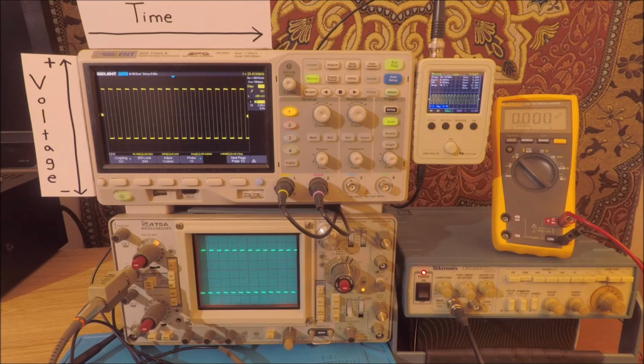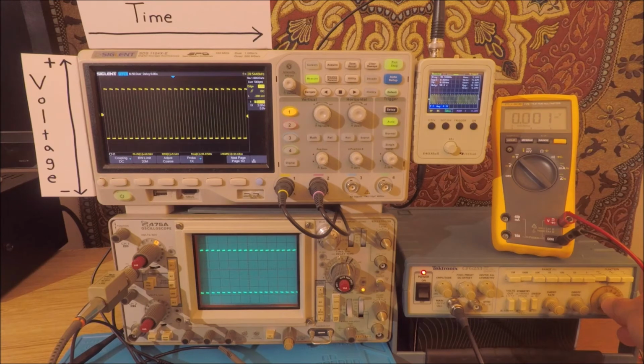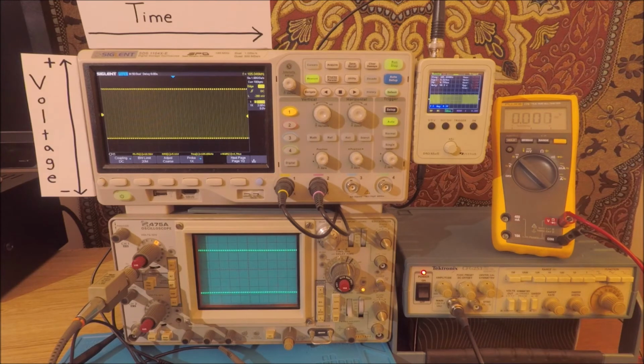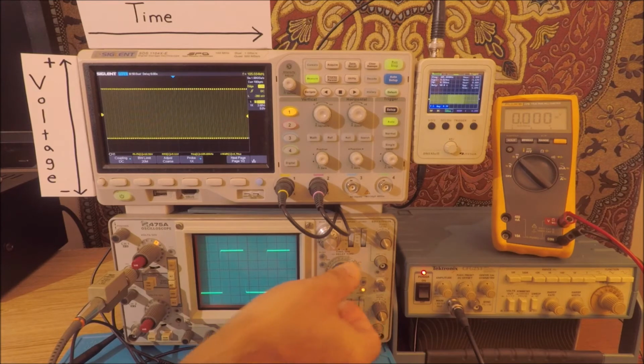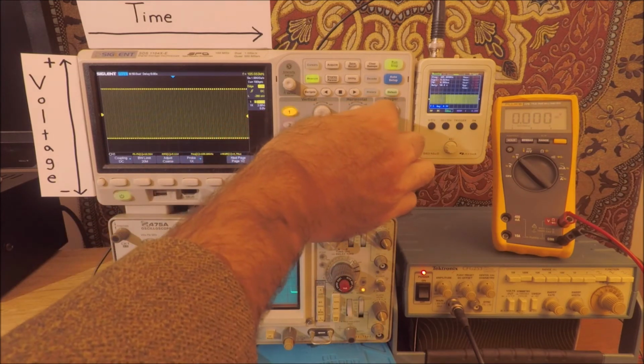And as we would predict, our voltmeter shows us 0 volts, so that's not very helpful, right? This is why we're using an oscilloscope. We can bring it up even higher in frequency. Here's 50 kilohertz. Bring it up even higher. Now it's getting hard to even see the signal anymore. We're up at 100 kilohertz now. So one thing we can do to readjust is to change our time scale. Now we see our signal again by zooming out in the time domain.